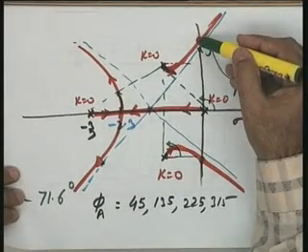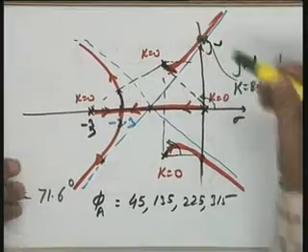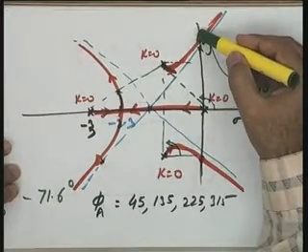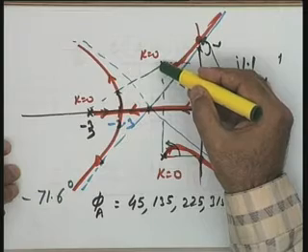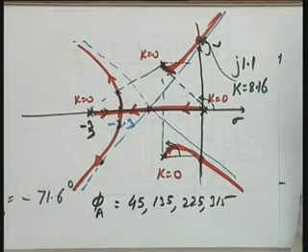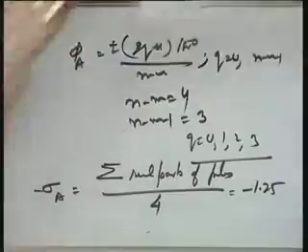And the corresponding roots of the auxiliary equation which I have found are plus minus j 1.1. So if this point is also available, and the angle of departure is available, in that particular case a rough root locus sketch can be drawn. Okay? Any question, please?